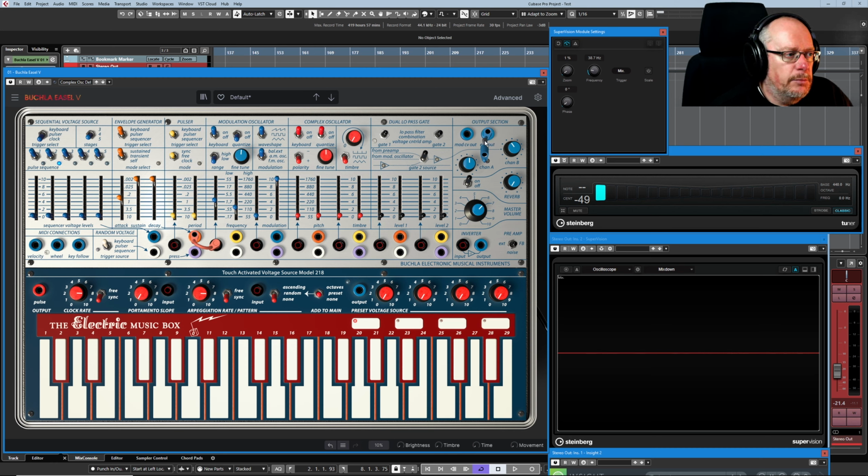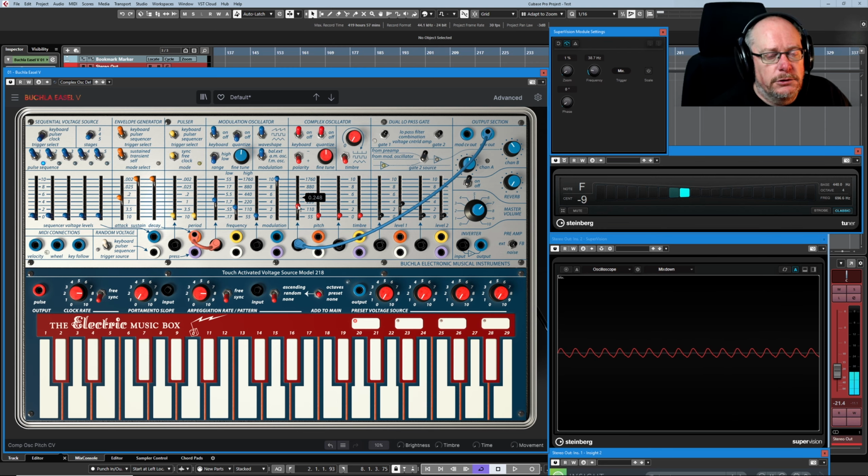So if I take this and plug it into my complex oscillator's pitch, get this running. So there's our standard, completely regular baseline complex oscillator. Now, without the control voltage input from this noise generator, we would have a tone at somewhere around 700 Hertz. What the noise generator is bringing to the party is the tiny wobble. That's what it sounds like when you use a noise signal as a modulation source. It's pretty damned unpleasant.